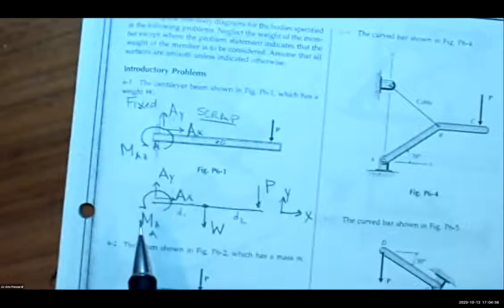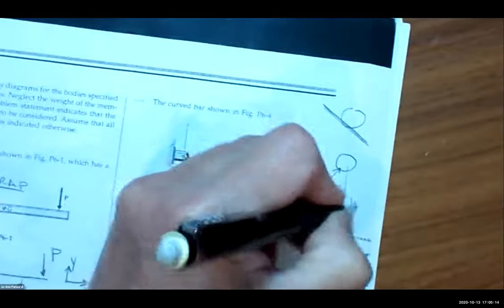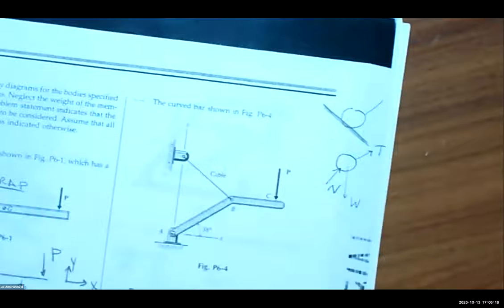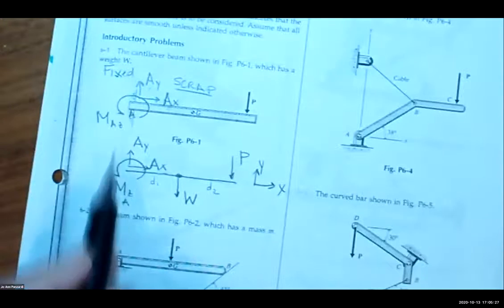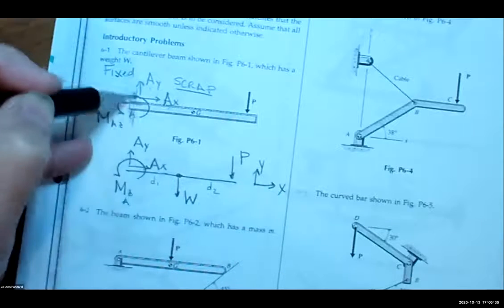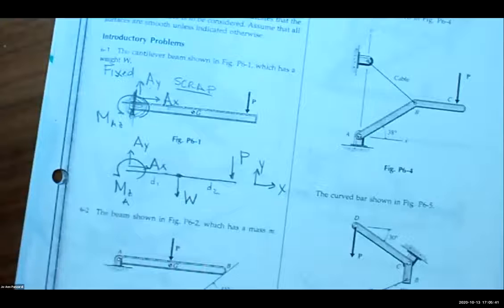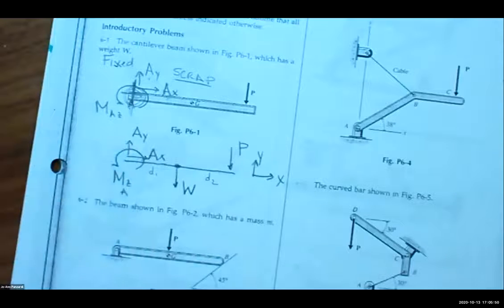Okay, Joanne, I just want to clarify. So basically, in this free body diagram, those are the forces from the connection on the beam, right? That's correct. Remember when we had a cylinder on a surface? We knew there was a normal between them. When we separated the cylinder from the surface, we had to account for that. We had to put the normal in. We had a weight in. And if there was a tension, when we cut the tension, we put T for tension. Now what we're doing is we're removing the beam from its fixed support, and we have to account for that movement away, right? So internal to the system, there is a force in the X that's equal and opposite. There's a force in the Y that's equal and opposite. And there's a moment equal and opposite in here. So when I remove the beam from the fixed support, I have to put those 2 forces and the moment in.